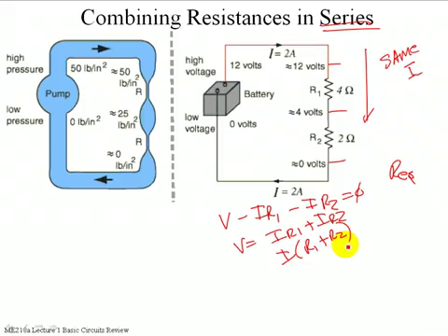They've calculated what this value is, and so they want to put a chain of resistors together, all standard sized resistors, to get to this exact value that they've calculated. They ignore the fact that the uncertainty in the large resistor completely swamps any knowledge or any value of the smaller resistor that you've added. So please don't do that.